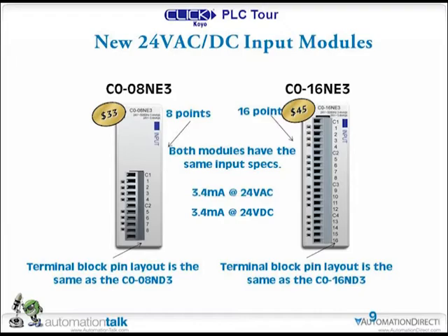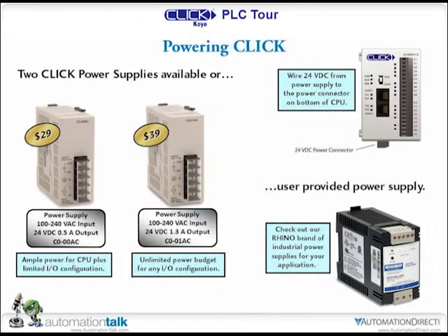These are really nice. And like I said, powering the CLICK, you can do it with an external power supply, like we've talked about here, or you can buy the optional ones that we've got. And with the optional ones, the cheaper of the two, as you can see, you're limited to a certain power budget. If you buy the more expensive one, you don't ever have to worry about a power budget. You can just throw it all the way up to 8 I/O modules and not worry about it. That's right.